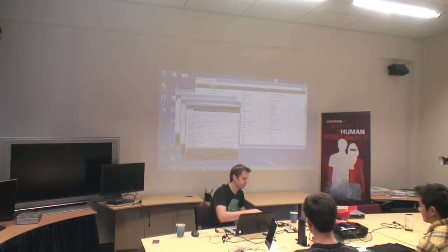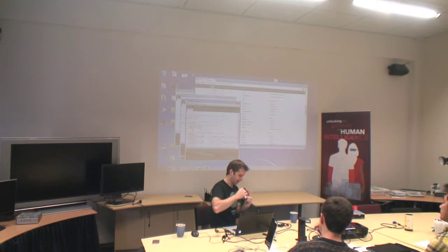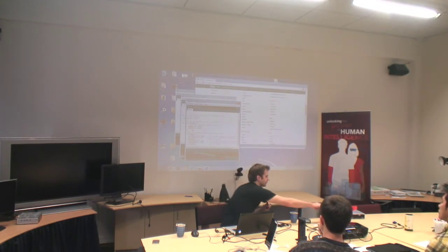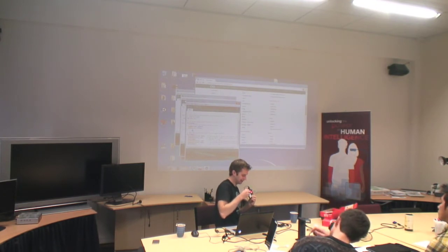Right, so I'll just give you guys a bit of a rundown on what's going on here. On the breadboard, we have rows of things we can plug into, obviously. Down here we have typically what's done as positive and negative strips. All of these are connected vertically. So this pin here is connected to this pin here, is connected to this pin here. All of these running up here are connected, and on the negative, all of these connected to here are negative.